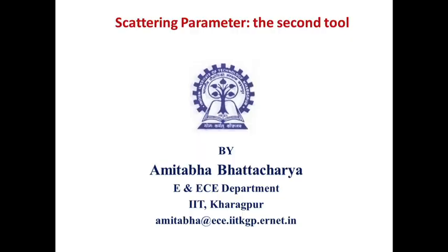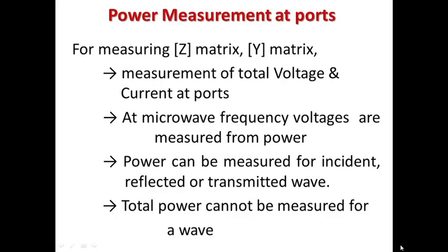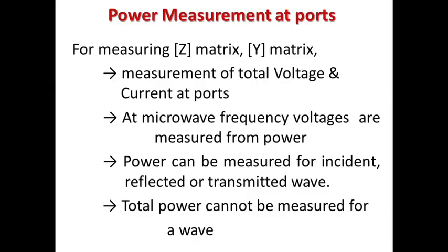Once we have defined equivalent voltages and currents, now we will see the scattering parameter, the second tool. We know that at ports we do power measurement, because at high frequency it is very much necessary that exactly at ports we define powers, because at other points the power measurement will be different.